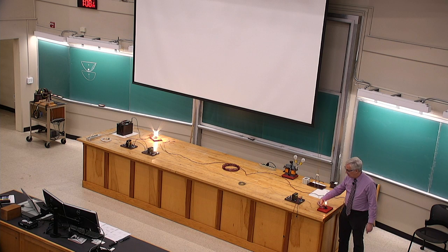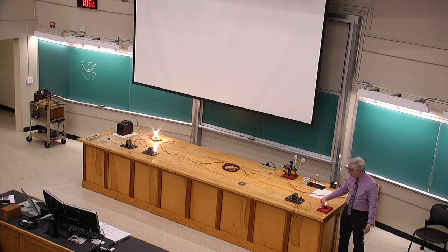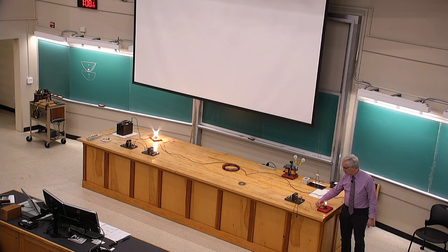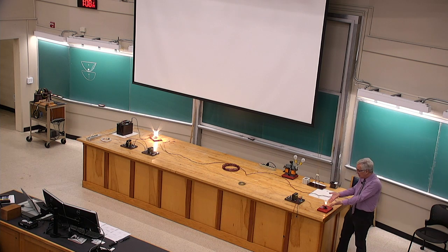And so the current that's traveling through here doesn't have as much energy per charge. And in order for it to go through the light bulb, and in order for it to get back through a second wire, which has a significant electrical resistance, that wire is going to consume some of its power. It needs some voltage left, some energy per charge. So not only does the charge arrive at only 8 volts probably, it has to leave at 4 volts to have enough energy to flow through the wire at the rate it's flowing. So there's only really about 4 volts left available to the light bulb itself.